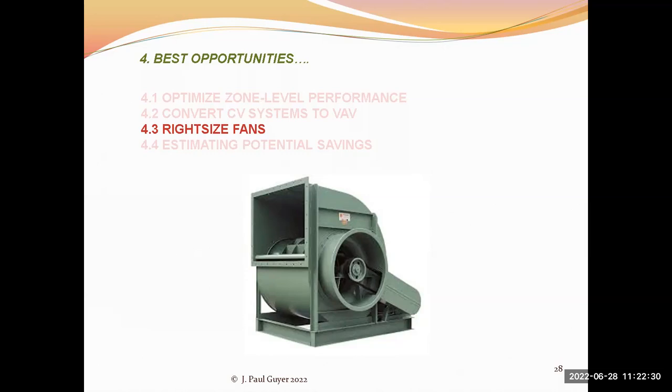And since the fan power is proportional to the cube of the speed, even small speed reductions can reduce energy costs appreciably. The new larger pulley should operate the fan at a reduced speed that still matches the peak load requirements.